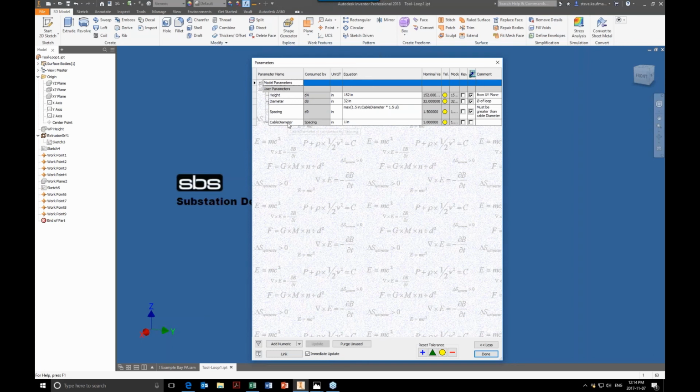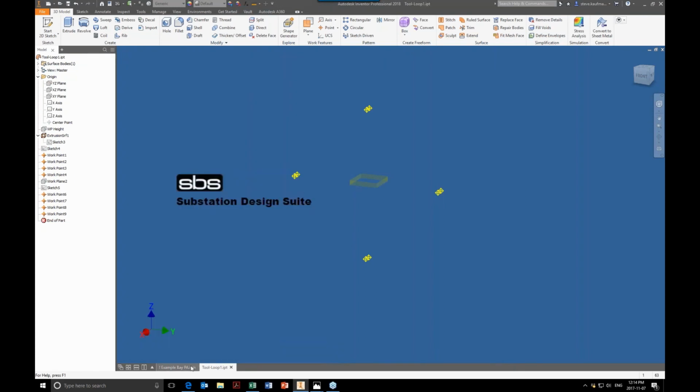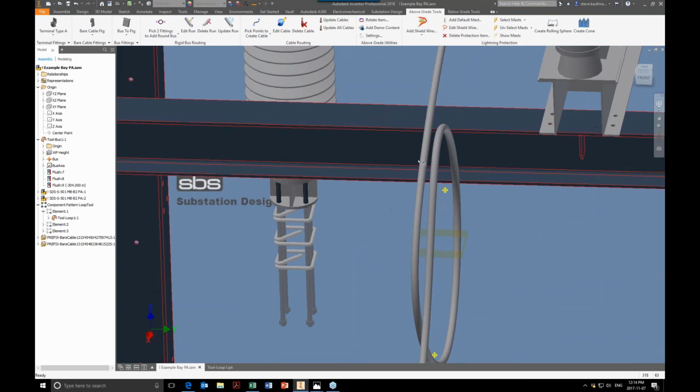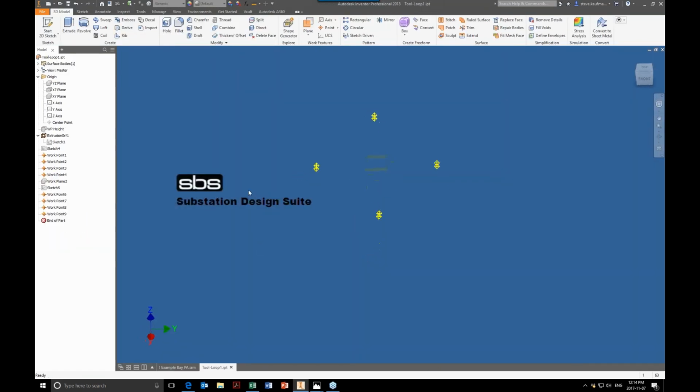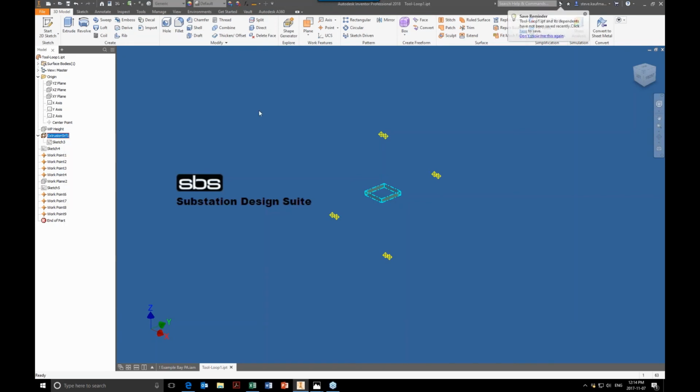I put in the cable diameter because what I'm doing actually when I'm passing through here, I'm passing the cable around itself, and I don't want it to collide at all. I want that gap in here, and I can adjust that gap with the loop tool. So if I were to adjust that gap now, adjust the diameter, I can update the cable, and it will show accordingly. This extrusion here, I just have as a surface extrusion. It's just for my reference. It just gives me an idea on where things are if I need it. But typically, I would have that visibility off.